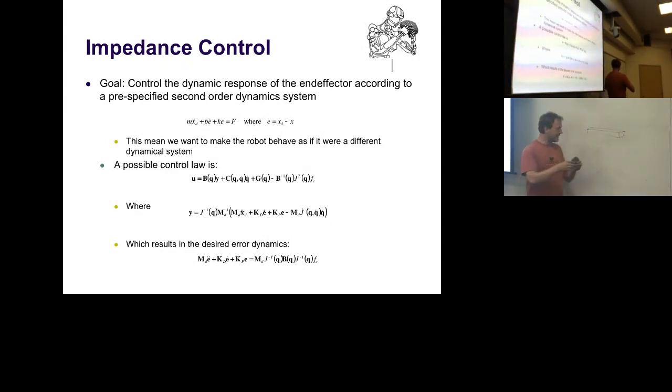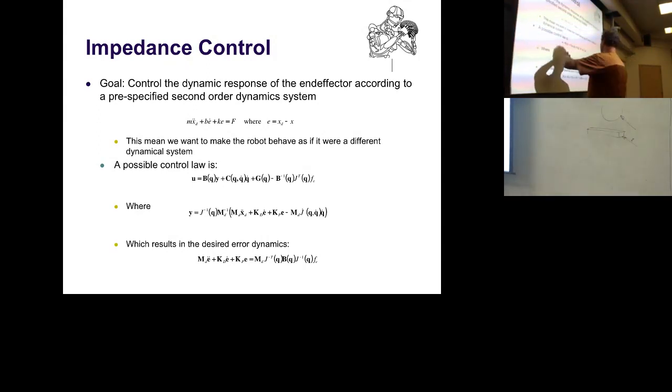And we have an object like this. And if you push it in this direction with a force, let's have a force here, it will not go straight up. It will actually rotate away. If you had a sphere, that doesn't happen. You push the sphere, it will just go straight up. No problem. This kind of anisotropy, meaning the inertia is different in different directions, gets compensated by putting the inverted inertia matrix in there, and you can calculate it out. It's a little bit annoying, but it's totally doable.